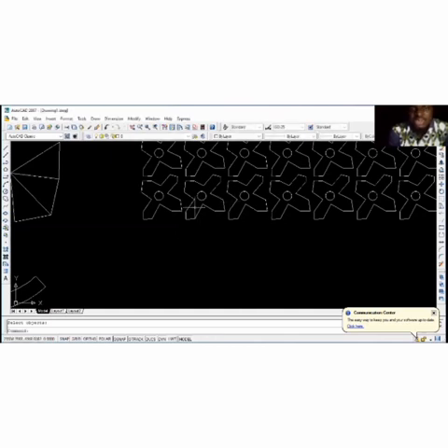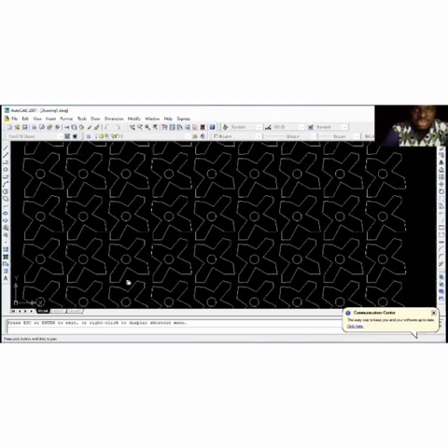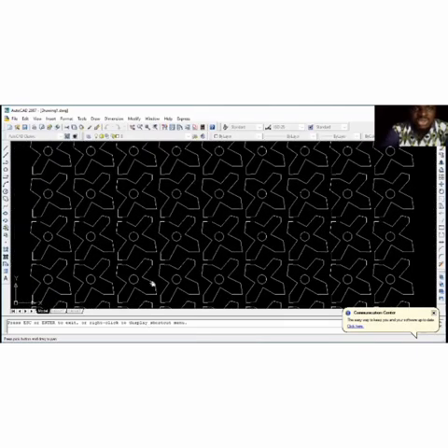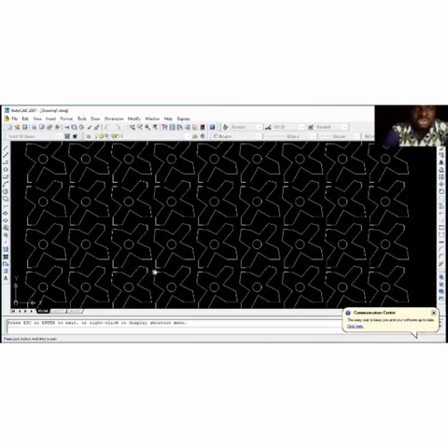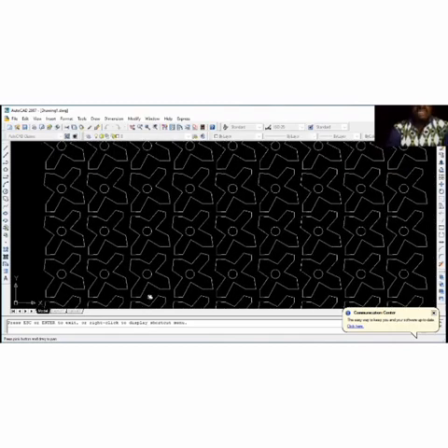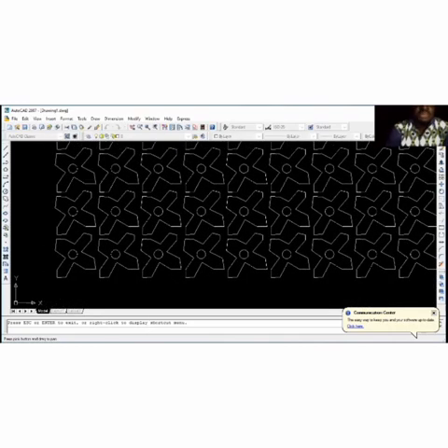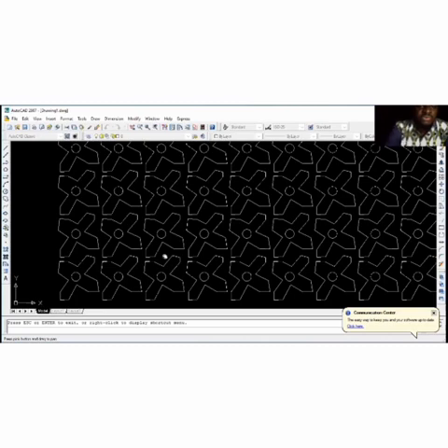Now after accepting this, we can pan it, P enter, and then drag it. Use left click and then drag, so you can see it. So that's what your array does. So you don't have to start drawing this one after the other. You can see we have exactly 5 rows there.